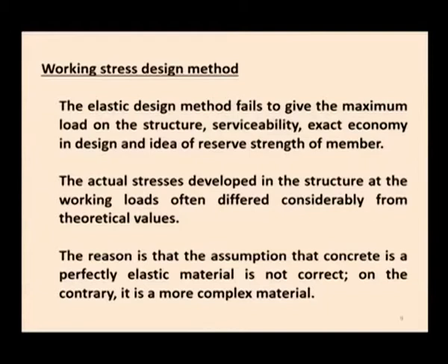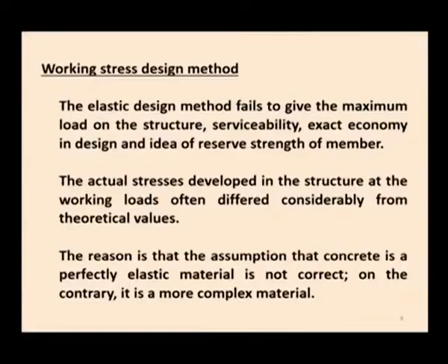Due to that, this method normally fails to give the maximum load on the structure, serviceability and exact economy in design, and an idea of the reserve strength of the member. Also, the actual stresses developed in the structure at the working load are completely different from the theoretical values. This is a second reason for the failure of the working stress method. The reason behind it is the assumption that concrete is an elastic material. Perfectly it is not correct. On the contrary, it is a more complex material. So, this is an introduction about the working stress method.